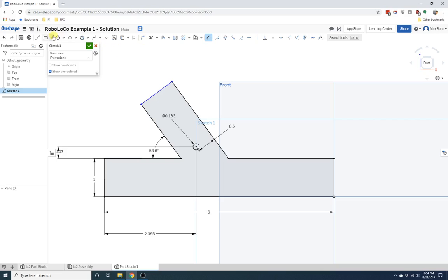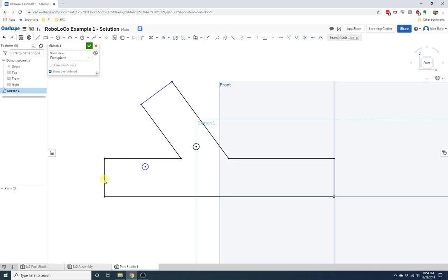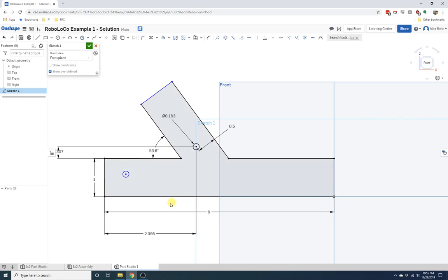Okay, we're also going to add a hole here for these on this bracket. And we're going to make the diameter of these two equal by using an equal constraint. Click that, equal. We're going to dimension this hole because notice it's blue, which means that it's not defined. So like I said, when something's blue, try moving it around, see what happens. See how I can move this in any direction. So I'm going to add a dimension here. What do we want this to be? 0.5.